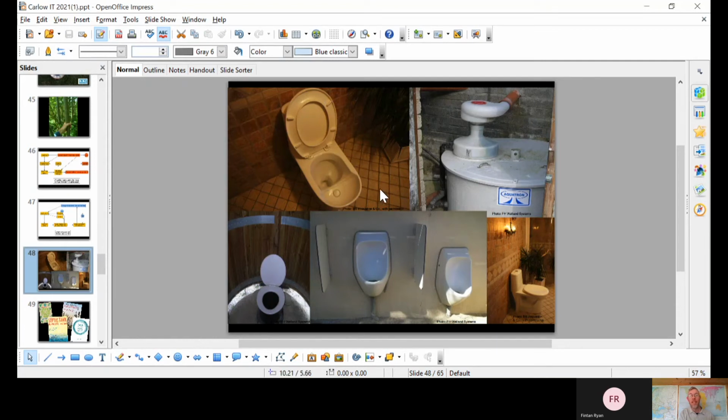Now, that's an easy way to recoup nitrogen from essentially fairly standard housing practice without anybody really knowing that the nutrients and the biomass are being recouped. And this is in a unit called an aquatron unit. It's a Swedish unit. The flush water comes in here from the toilet, swirls around inside in the vortex separator. There's a half tire unit here essentially that gathers that water and routes it off to the constructed wetland, and the solids then fall into the compost chamber underneath.